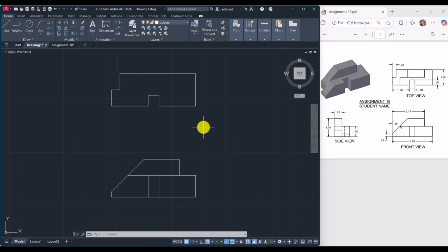If we look at what we need, you're able to kind of follow some lines from the front view. This is the reason I'm doing this with you. More practice, and also transitioning, drawing 2D, creating 3D from it. So we're going to start the line command, and notice this line in the top view comes from right here. So I'm going to rest my pointer there. Okay, pull my mouse up right there, click.